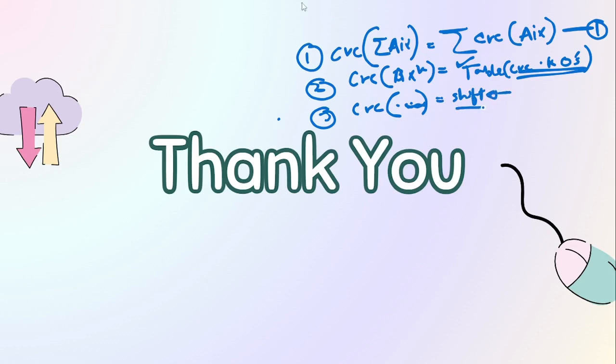And this happens because they haven't yet reached the top level. The CRC only evolves if you have reached the top level. That means if you have not reached the top level, you're just shifting left, right? And so this can happen in the last clock cycle only for CRC bytes. It does not happen for data bytes because by definition, every data byte has to go all the way and it has to be passed.